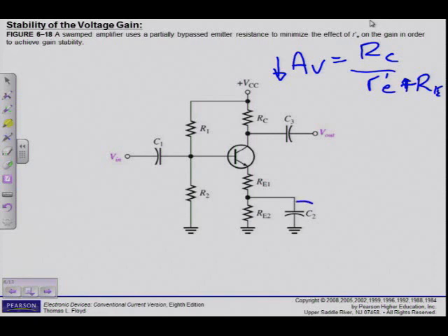Because I know my capacitor blocks DC. So if my current flows through one 1 kilo ohm resistor or two 500 ohm resistors, it remains the same, isn't it? But where's the difference? The difference is when I'm looking at my AC signal. What happens with the AC signal? Remember, for the AC signal, the capacitor acts as a short. The current's going to flow through there. But now it has to flow through RE1 and then there. So I'm only bypassing RE2.